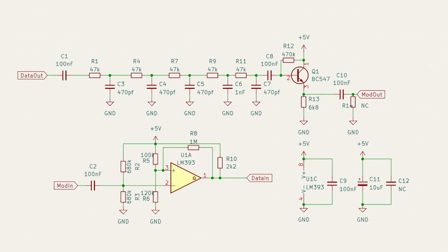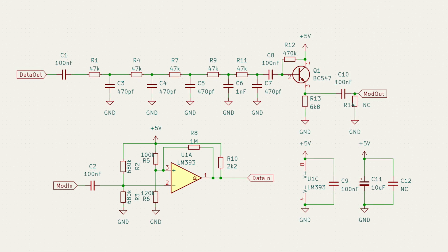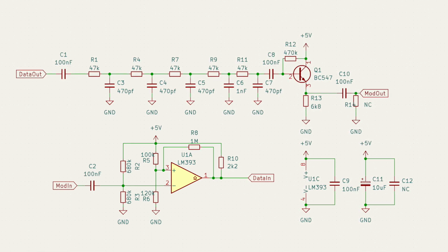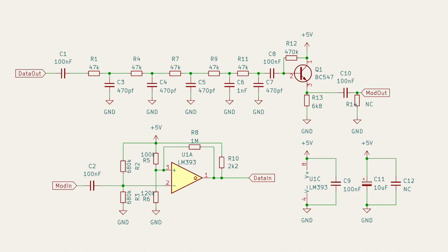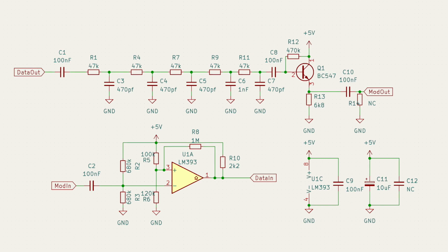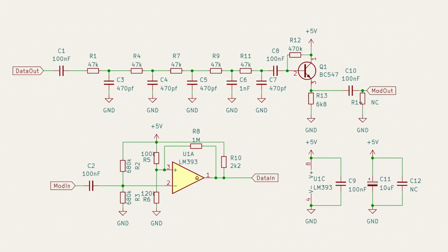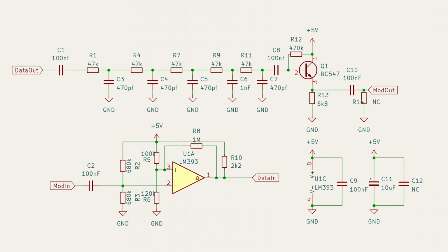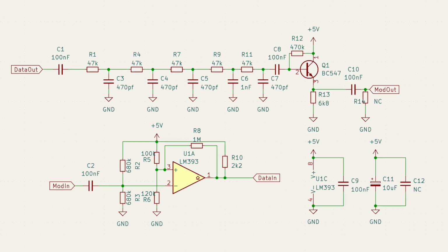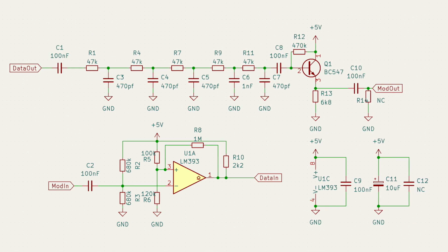If you're being really pedantic, you might say that this isn't a modem at all because it doesn't do a complete job. The modulator only takes a square wave input from the data out line and smooths it into something resembling a sine wave with a bit of buffering. I would say that it barely qualifies because it does turn a digital signal into an analog one and thereby making data into audio, even though it does need the computer to do more of the lifting than just provide zeros and ones.